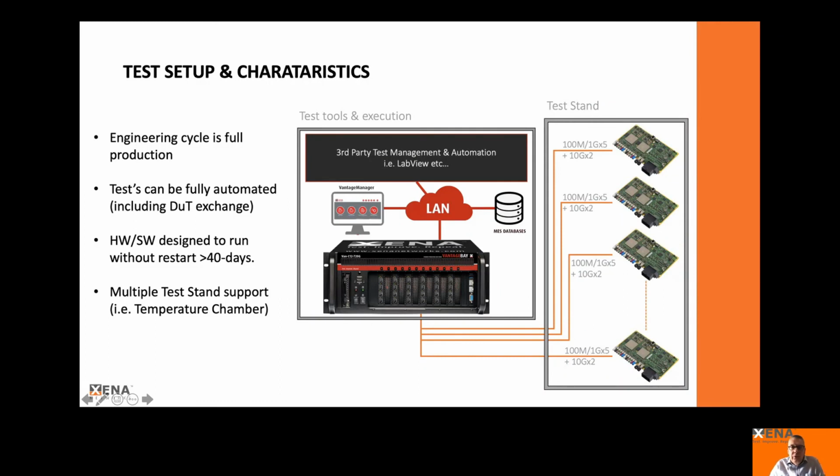The test setup is also pretty simple. So you have again a specific test system like the Vantage Bay, which is connected to again a third-party test management and automation tool, or to our own Vantage Manager, which you will see shortly in the video presentation. And then the test solution system is connected to the test stand, where you can put in multiple ECUs or multiple end devices to be tested in parallel.